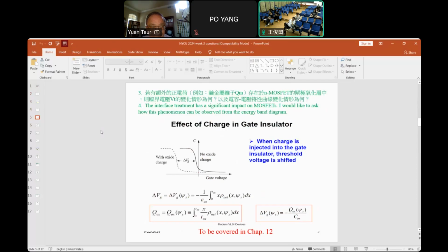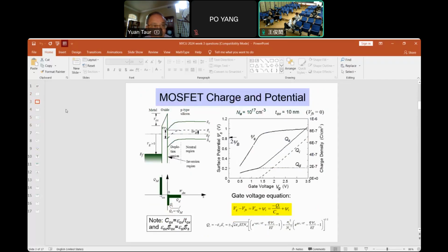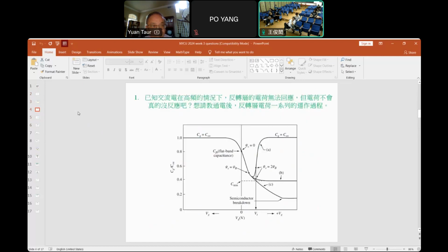Okay, so that's it. And also for the previous question, in terms of the inversion versus depletion layer small signal, MOS capacitor and MOSFET are very different. In a MOSFET, you don't have any supply of carriers, right, except from generation. So generation usually is slow, especially at room temperature, unless you have very dirty substrate, have a lot of generation centers. If you are in a MOSFET,